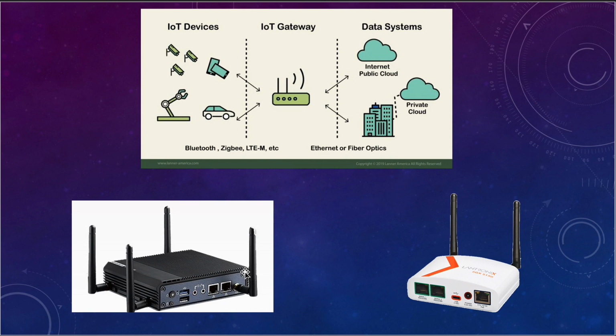But when they want to connect to the internet through the existing network of the building, they have to use devices such as shown here, gateway devices, which understand protocols such as Zigbee, Z-Wave, and LoRaWAN, which are dedicated to IoT, and convert them into normal standardized protocols used in internet communication, so that they can communicate with the cloud.